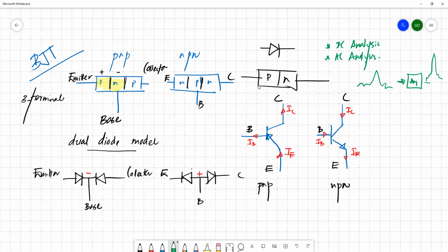Why we need DC analysis is to make your transistor work at a particular level that we want. If it is an amplifier, we need to amplify the signal, so initially we need to place the transistor to work at a particular point. To bring this transistor to this workable mode, we need to have this biasing. With this biasing, we manage all these DC quantities in the circuit and find out whether we can place the transistor at that particular operating point. This process is the DC analysis part. On top of this DC analysis, we can bring external time varying inputs to the system, make them amplified and send them to the output. So on top of this DC signal, we may feed time varying quantities to this circuit.